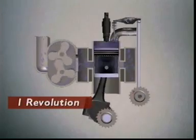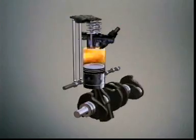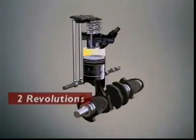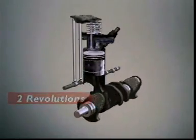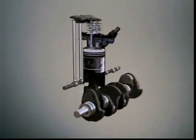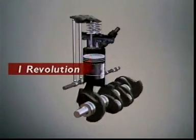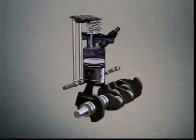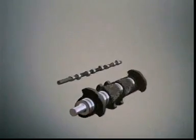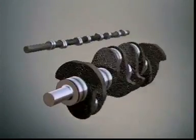How does this compare with a four-stroke engine cycle? How many revolutions does its crankshaft complete from intake through compression, ignition and power to exhaust? It makes 2 revolutions. In that time, what happens to the valves? They open and close once. So the cams must make just 1 revolution, and if the cams make 1 revolution, so must the camshaft. But in each four-stroke cycle, the crankshaft rotates completely twice, so the camshaft must rotate at half the speed of the crankshaft. This can be achieved by gears.